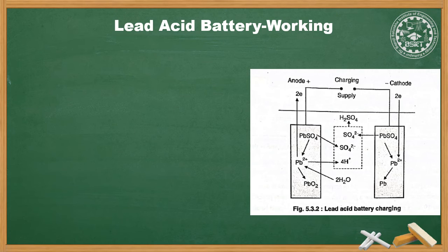The chemical reaction takes place between three chemicals in the battery. In the presence of H2SO4, the electrons from one group of plates collect on the other group of plates. The voltage of the cell is created due to the ions, charged particles, being forced into solution from the electrolyte by solution pressure.